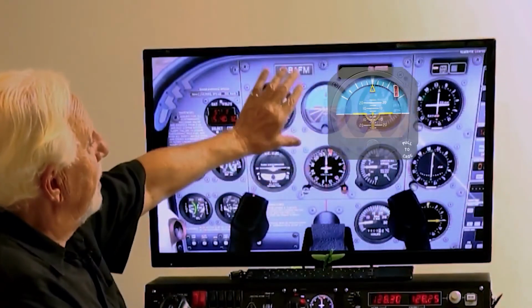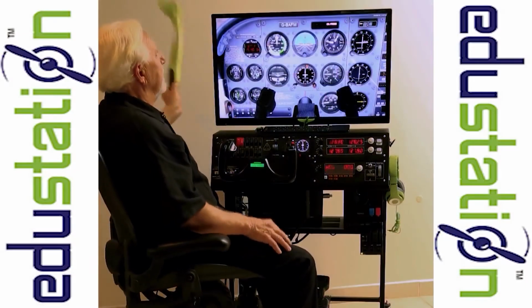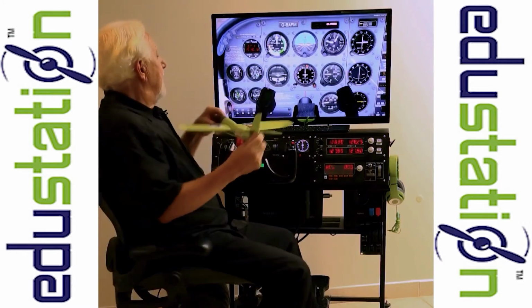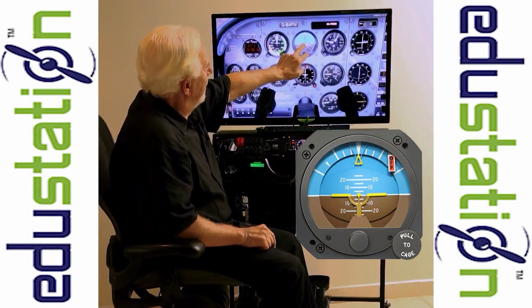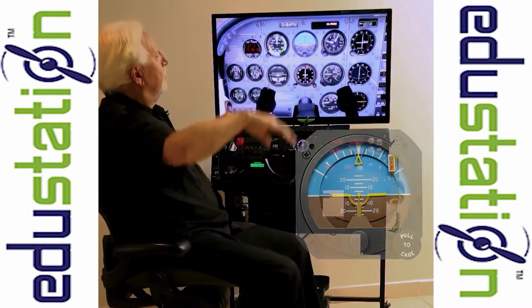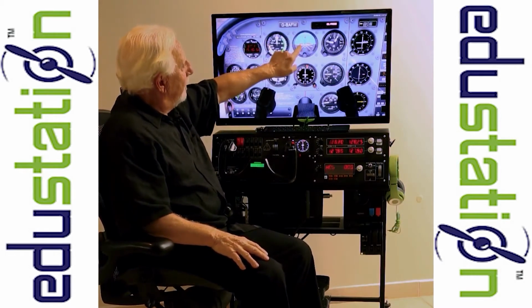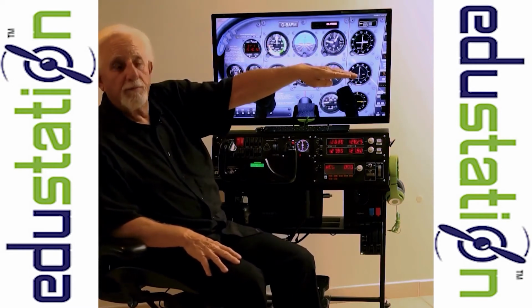The middle instrument is called our artificial horizon, and the artificial horizon is telling us our relative position to level. The orange line and the orange dot is your airplane. The white line is level. So if you're able to cover the white line with the orange line, your airplane will fly perfectly level.